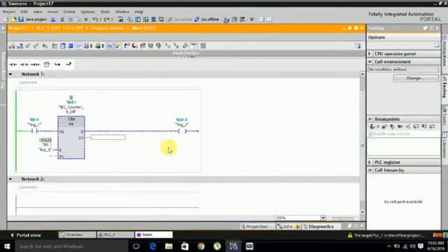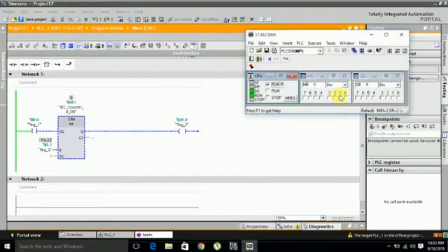Okay, we'll start. You see, till now our counter is not enabled, it is off, and its value is also false because we have not reset. Its target value is 4 and the counter has 0, and our output is also off.